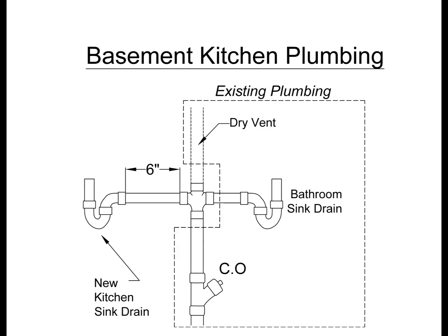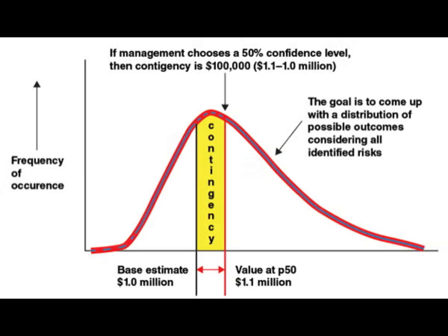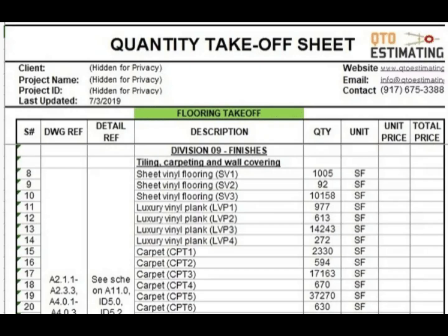Step 8. Apply engineering allowances carefully. Allowances should be applied intelligently, not automatically. Typical allowances may include a small percentage for pipe cutting waste or bolting losses. All allowances must be documented clearly. Never hide allowances inside quantities. Transparency is critical.